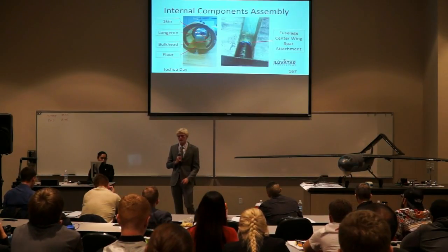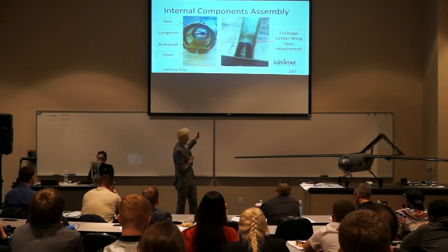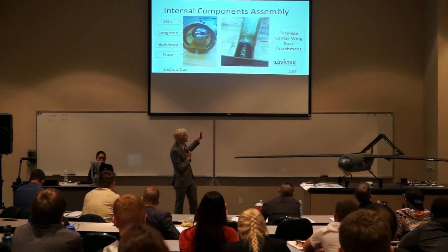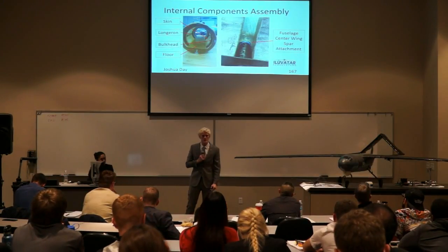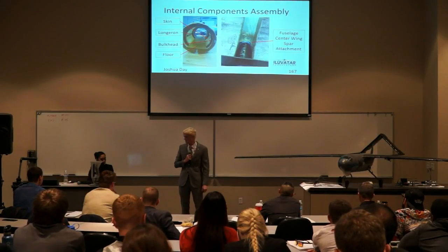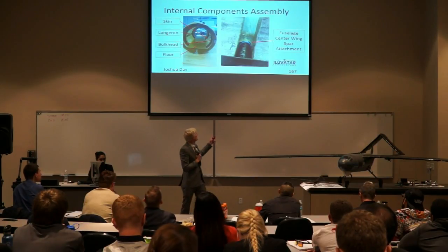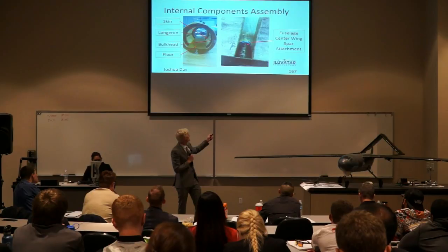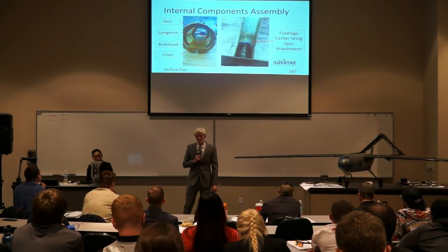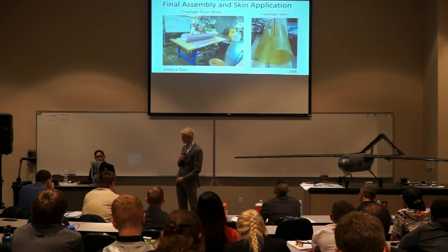The internal components of the floor were epoxied onto the bottom flat section of the bulkheads, and then flanges were used along this front edge as well as along 3 bulkheads in order to help with the impact from landing, so that the floor would not come up off of the bulkheads. The center wing was attached by drilling a hole through the fuselage skin and going through the internal fuselage ribs, and the boom would be slid in and then the wings were attached.